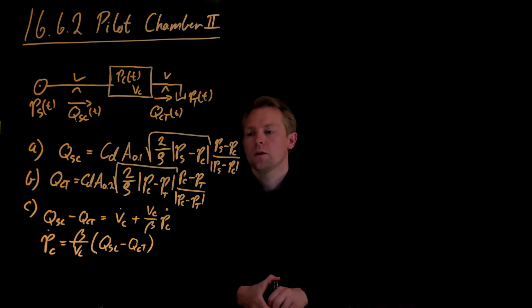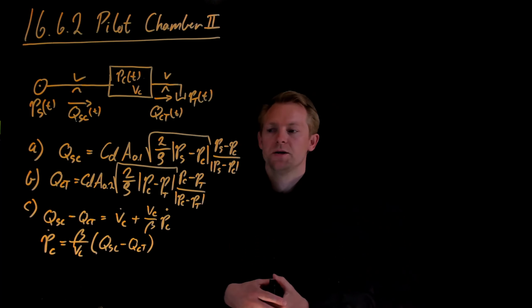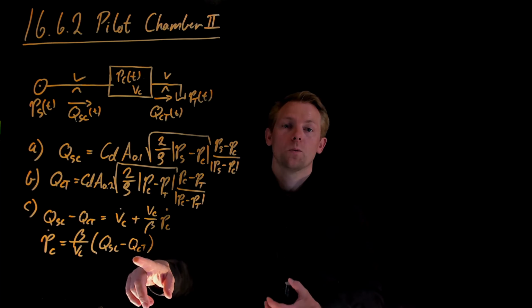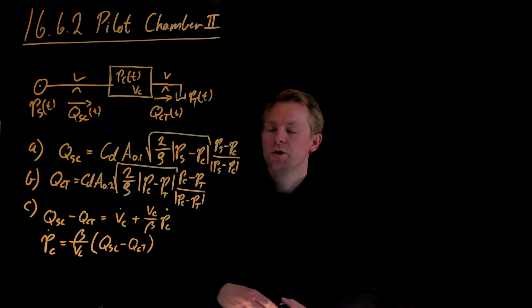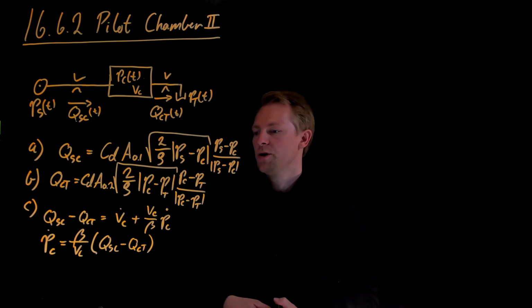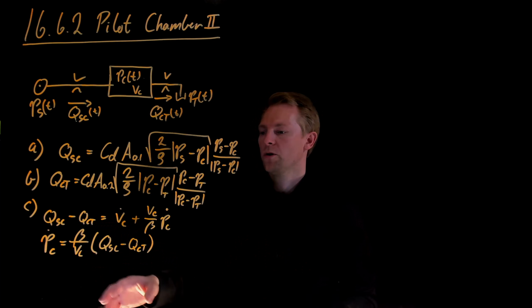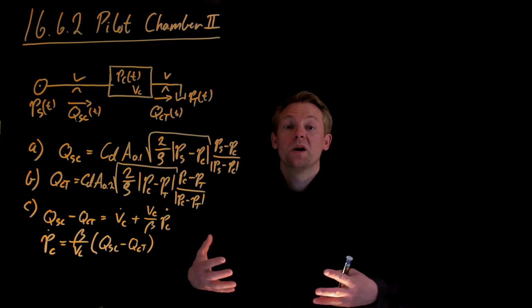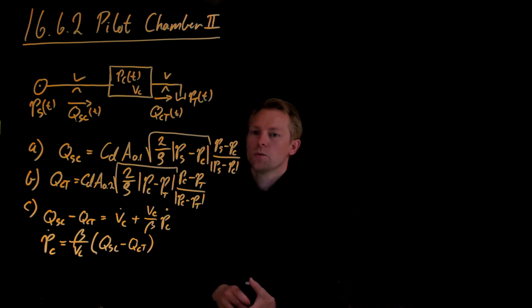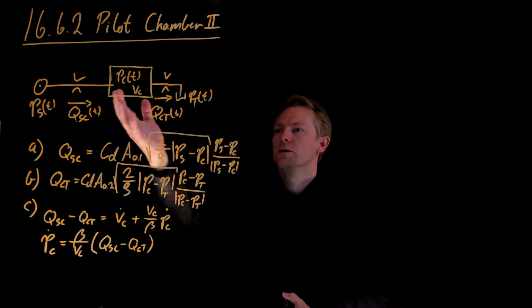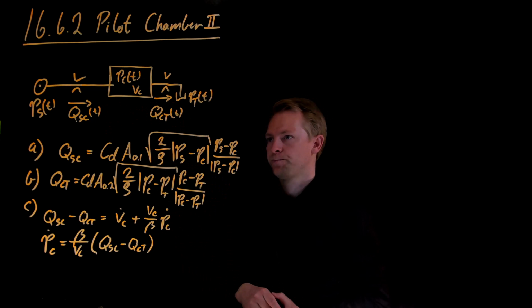And having the model, it's always nice to do a small sanity check. If the flow in is larger than the flow out, what will happen with the pressure? Well, it will increase. How much it is increasing depends on the stiffness of the oil, or the bulk modulus of the oil, and the volume that we have. How big is that volume? So we could say that this is our time domain model for the system that we have up here.